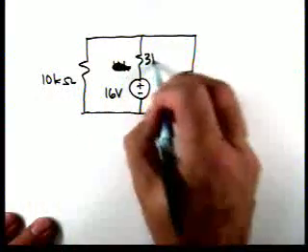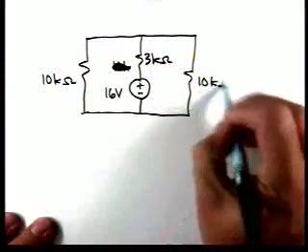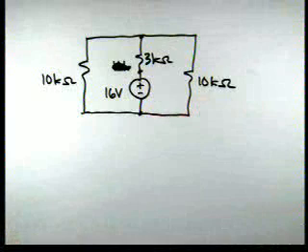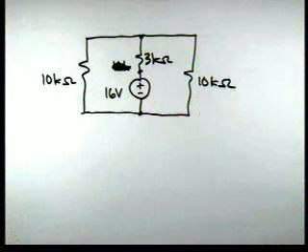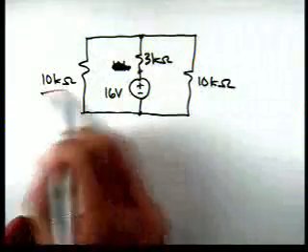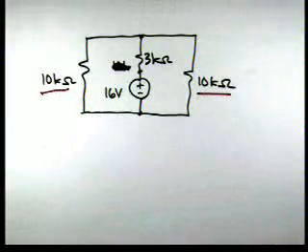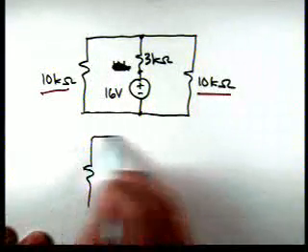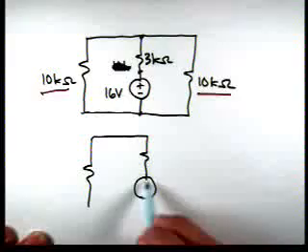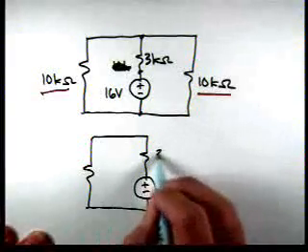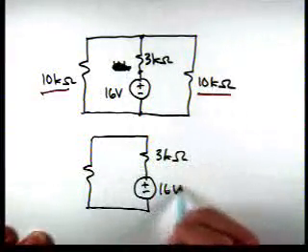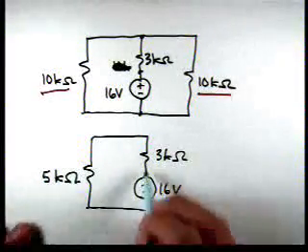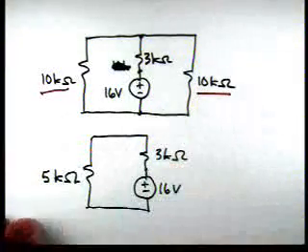Okay, this is a 3 kiloohm. Here's a 10 kiloohm. Now, V1 no longer appears in this circuit because that 4K resistor was combined in series with the 6K. Now, if we notice, these two are in parallel. So now our circuit can be reduced to the following. Two 10K resistors in parallel is a 6K, or excuse me, a 5K. So now we've got two 10Ks in parallel as a 5K.